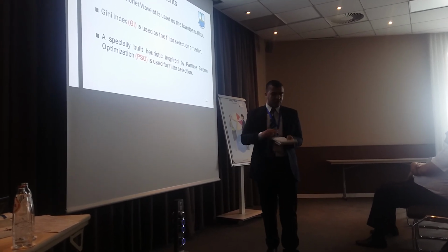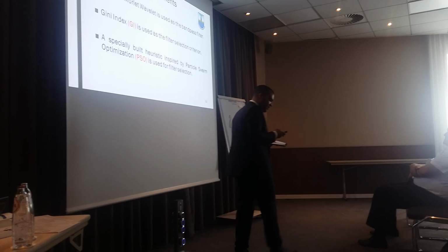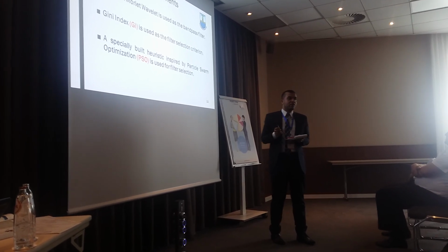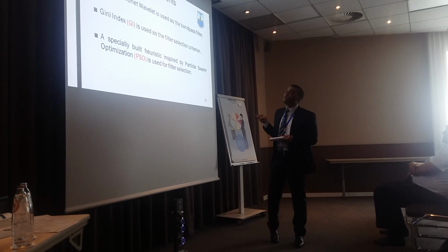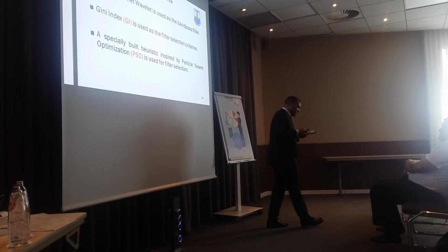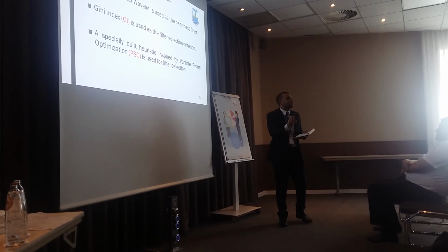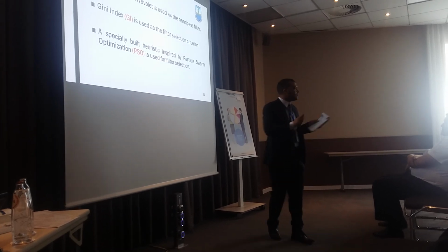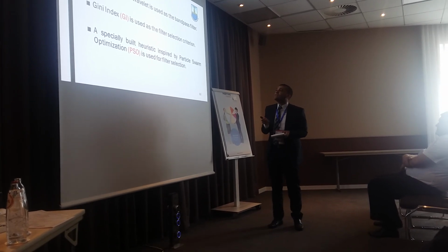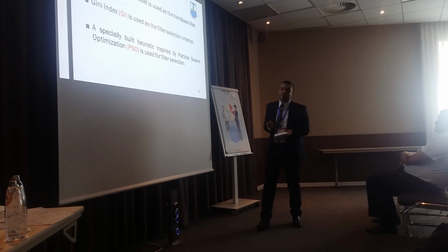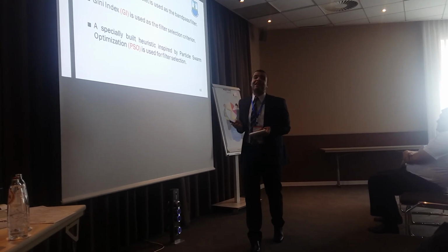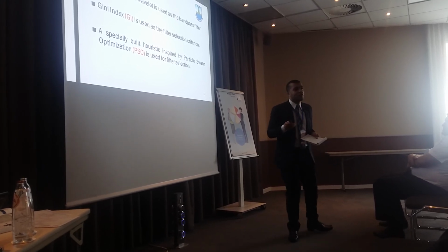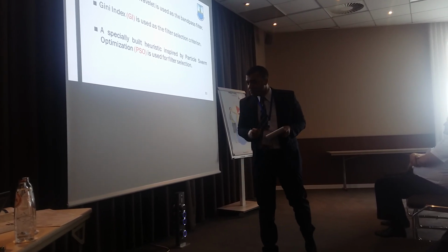The developed algorithm consists of three main components. The first component is the complex Morlet wavelet, which is used here as the band pass filter. We chose it because it has a shape similar to the shape of the vibration produced by a mechanical impact in the time domain. The second component is the Gini index, a statistical sparsity measure, which is originally used by economists to analyze wealth distribution.